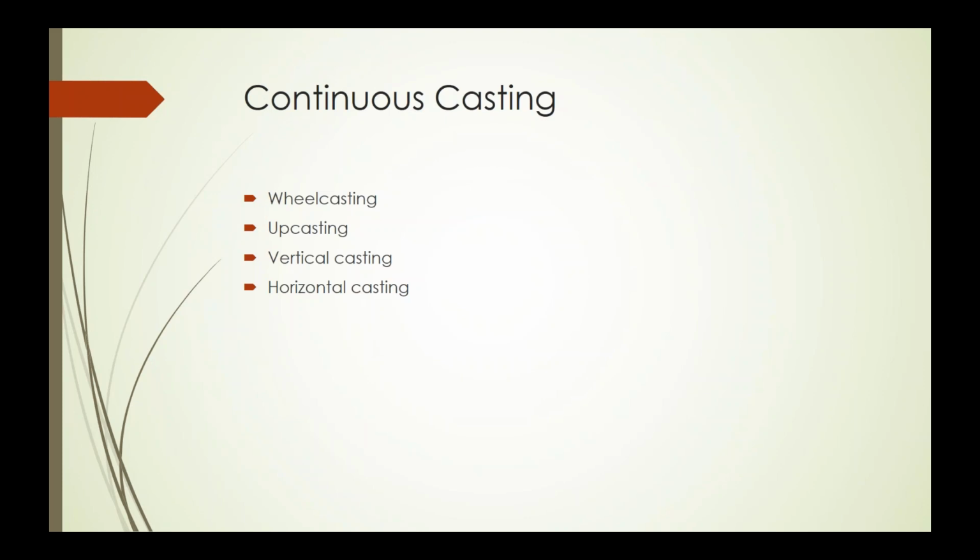Vertical casting, usually in a continuous form, is a vertical drop, as opposed to the upcasting techniques. And then horizontal continuous casting. Those are a specialty area many times for long solidification temperature alloys.